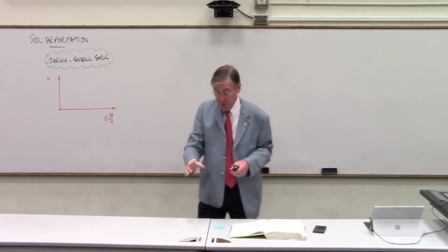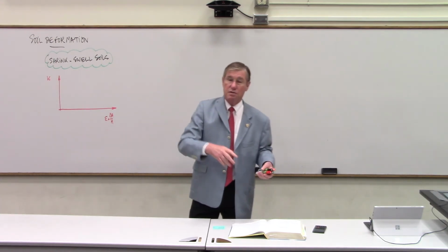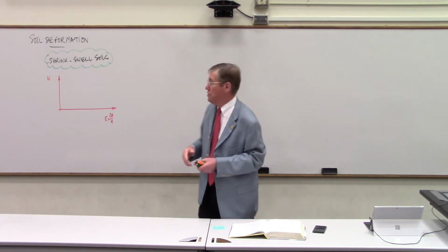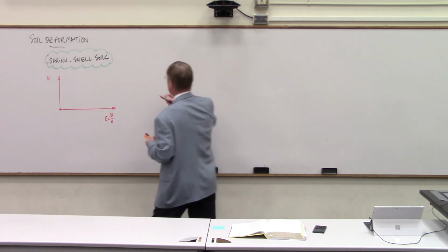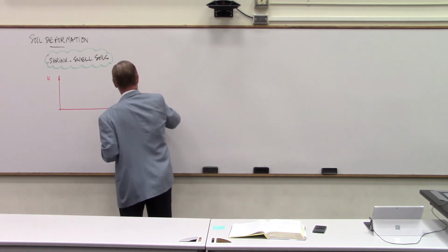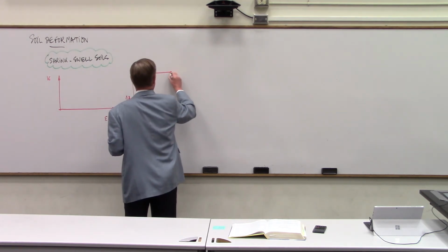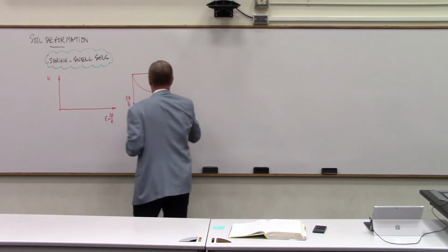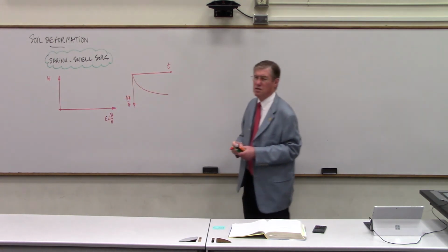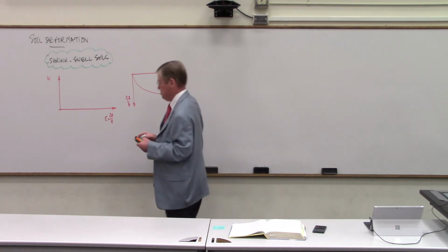So we have this material, we come back 2 hours later, we weigh it, we measure it in 3 hours, inside the next day, and so on. And then we're able to plot the shrinkage of the material. So we can plot delta H over H as a function of time, and it goes something like this, right? Usually after 24 hours, the material has shrunk almost all it will shrink.